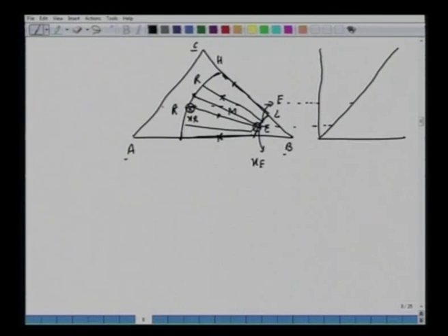So again, you do the same thing as we did earlier when you took the projections like this and extended this component here. This will represent your E and R. This coordinate which comes from here is XR, and what you are reading here is your Y. So this YE is the extract phase composition, XR is your raffinate, and you get this line.